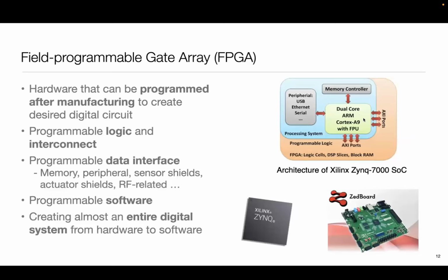So FPGAs have that flavor: you write your algorithm in some high-level language, it translates into a configuration file, and then that configuration file is loaded into the FPGA to give it a specific hardware functionality. Almost sounds like a hardware processor, but obviously not as flexible. You're still working at a lower level, but you gain in performance and all.